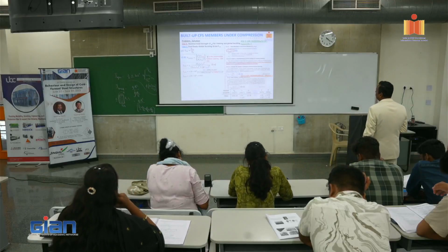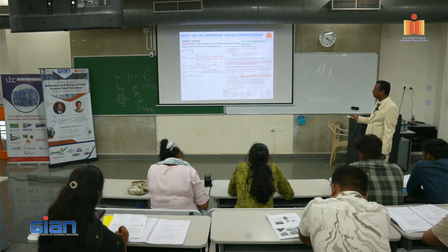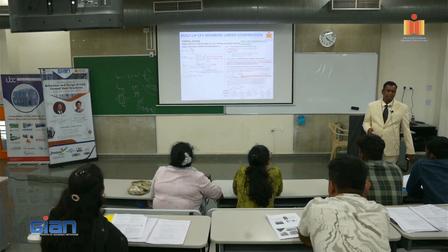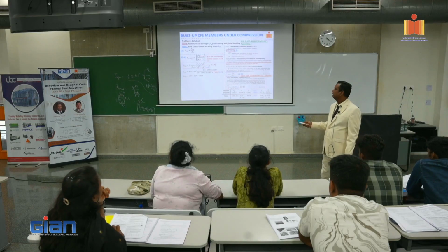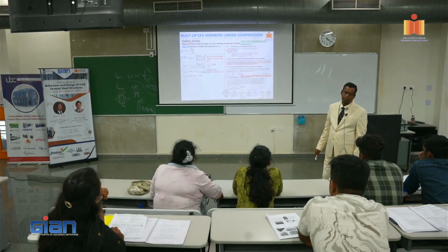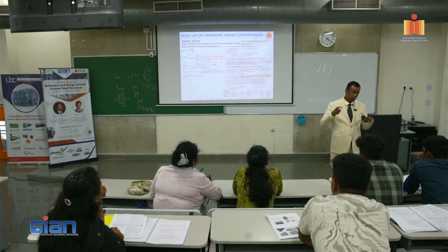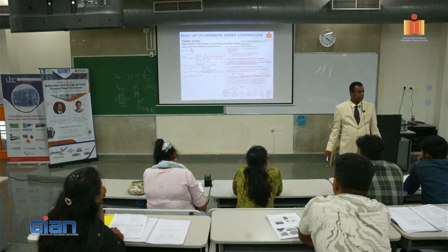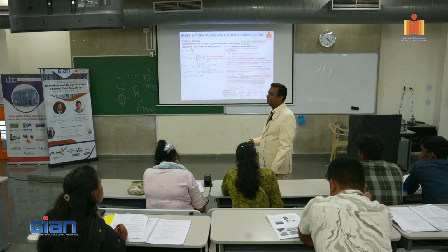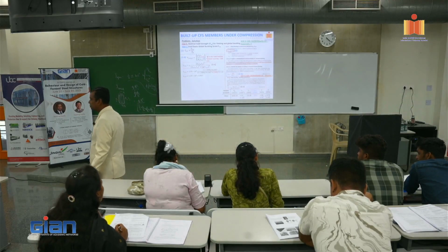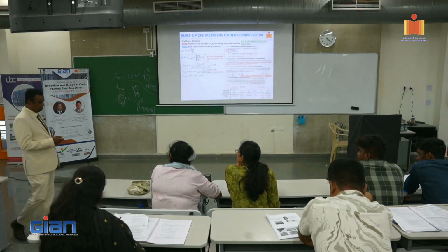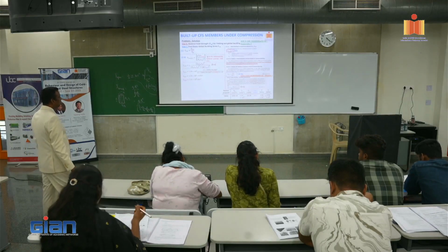Okay, now you do so, you get 1.59 into 0.957. What does it indicate? This indicates this fellow is a reduction factor. You are penalizing because it is discrete. If you run the numbers, instead of 300, if you put 100, you will get a much closer number to 1. You understand what I am saying? So more the fastener spacing, greater is your reduction factor. Lesser the fastener spacing, you are closer to continuous, right? So the code inherently accepts that there is some reduction that has to be made if the fastener spacing is not continuous, it is discrete, and depending upon the spacing or the discrete distance, you have to adjust and come up with a factor. So RIY equal to 1.52.